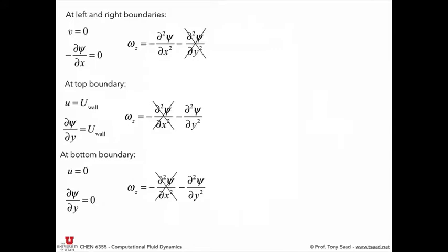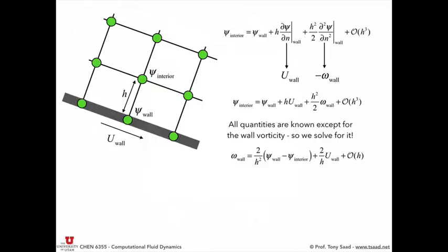It could be 0 if u wall is 0. Even dψ/dx is v wall, on the left boundary. It's the speed at which the wall is moving. It's dψ/dn, normal to the wall. So the derivative of the stream function normal to the wall is really the speed of the wall. So then we can convert this to u wall, which we know, checkpoint.